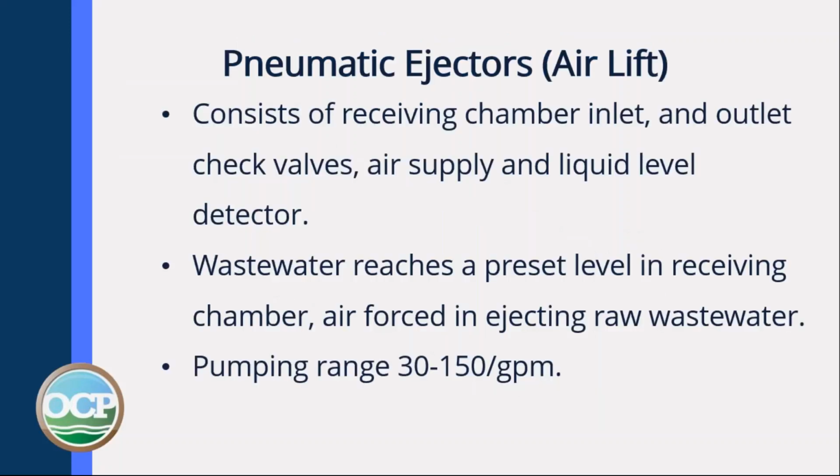Pneumatic ejectors or airlift pumps. They consist of a receiving chamber inlet and outlet, check valves, an air supply, and a liquid level detector. When wastewater reaches a preset level in the receiving chamber, air is forced in, ejecting the raw wastewater. The pumping range is between 30 to 150 gallons a minute.